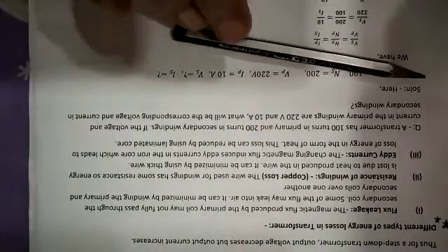If we use thicker wire, and we know that thicker wire has less resistance than thinner wire, we have already learned this in class 10. That means instead of using thin copper wire, if you use thicker copper wire, the loss of energy decreases. That means the resistance of the wire decreases. As a result, the heat produced in the wire will also decrease. That means there will be less loss of energy.